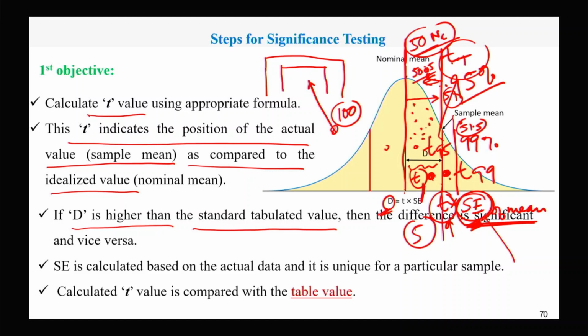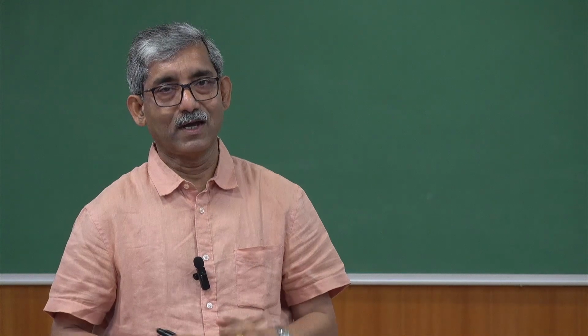So if we cross the 95% significance level, we see that there is some evidence that a difference is there, but it's not that significant, so we don't take action. But when it crosses 51.5, that is the 99% level, in that case we should stop the machine and readjust the yarn count.